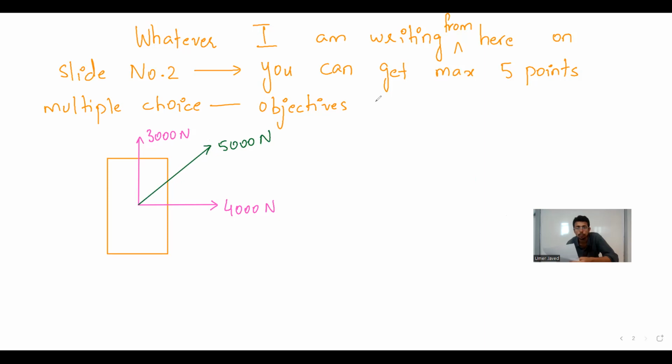Now, what is the length of the beam? The length is 10 meter, right? Remember, I told you the cantilever beam is 10 meter and you are looking at the maximum moment that is happening at the support. Everyone knows, right? In a cantilever beam, the maximum moment is at the support. Okay. So now tell me, what will be the formula?